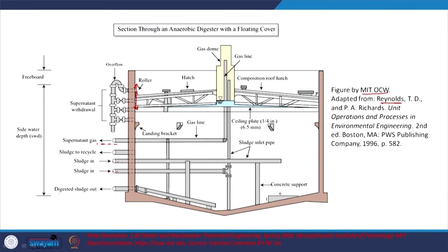Obviously, you have to remove the digested sludge from time to time, based on the mass balance, and sometimes recycle sludge. You have to maintain the relevant thickness of your anaerobic zone. Digested sludge out can typically go to farmland or agricultural land or to your gardens. That is something to keep in mind. So, let us move on.